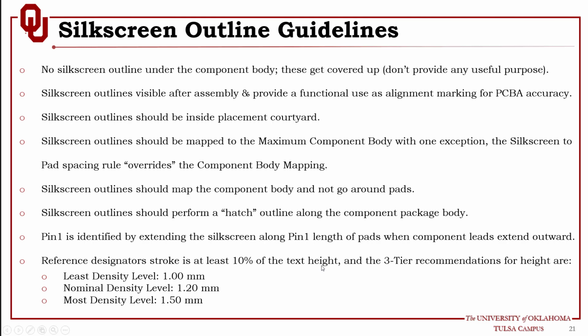When you define the designator, which is a text, the thickness or the boldness of the font should be 10% of the text height.